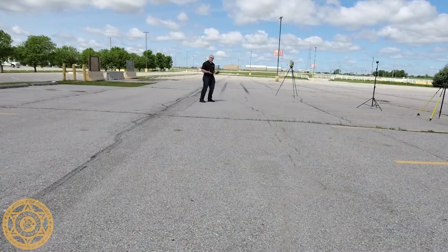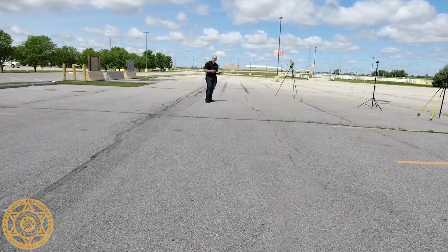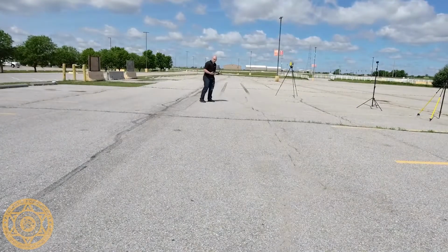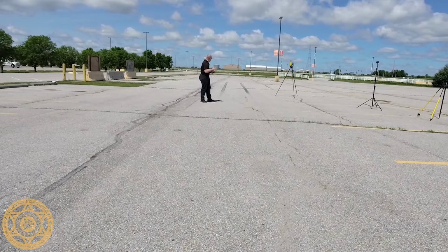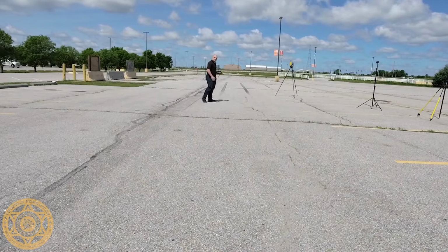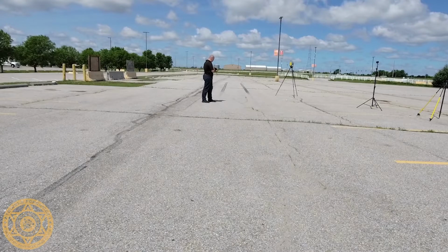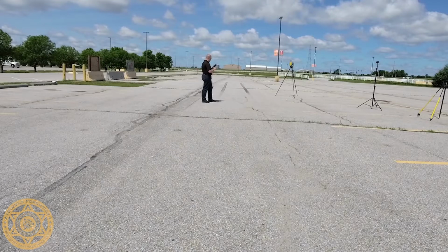Now this is the interesting part: how do I document where that is? Well, when we were talking about our X7 having a unique feature, the X7 has the laser pointer, or precision point feature. This is something that no other laser scanner on the market is going to give you, the ability to have it work like a total station. One way we could mark this is to put down some chalk. But another option is to turn on the laser pointer and have it point at my toe, and we're going to document where this is.